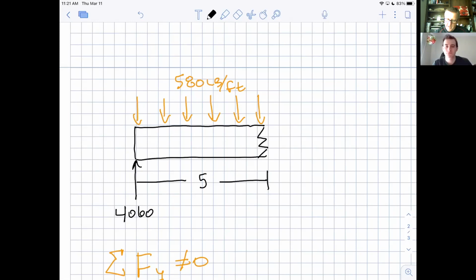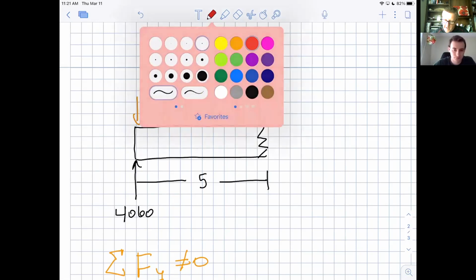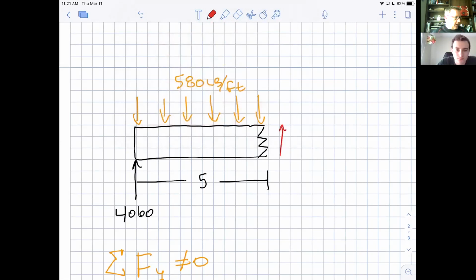And so we can actually come back here just like we did for the supports and say, this is not all the arrows that are in this picture. If you chunk it up like this, there's actually what's called a shear force over here. And I'll draw it. We'll talk about this in a minute, but I'll draw it downwards. Now learn that word, shear. What is shear? Shear is a beam or some member doing what I just showed you, which is sliding past each other.